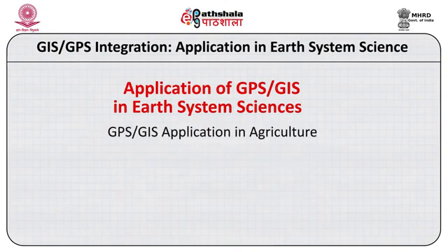Use of GIS GPS application in agriculture. GPS GIS technology is used to locate and map the areas of high weeds, disease and pest infection. GPS is helpful in soil mapping, allowing the farmers to develop contour maps showing fertility variations throughout the field. For certain precise agriculture applications such as crop planting or topographical map generation, sub-meter DGPS accuracy is not enough. In such cases, a centimeter level solution using real-time kinematic can give greater accuracy as well as huge savings in time and money.